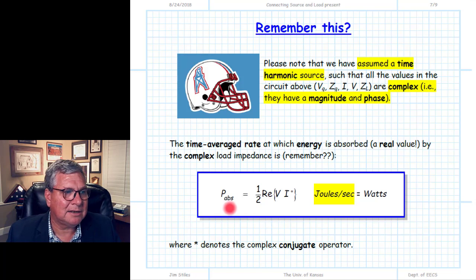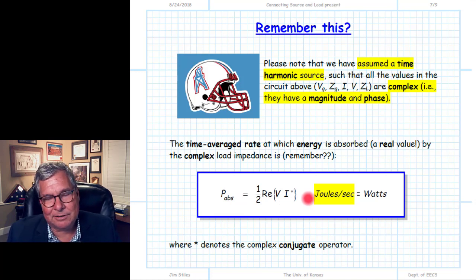And so a lot of times I get power is equal to V times I, multiplying a complex voltage times a complex current, and that's the answer. That's wrong in many ways. Again, you get a complex number, it has to be real, it has to be time average divided by 2. Make sure you take the complex conjugate. Lots of mistakes happen here. Make sure you understand, we're not talking DC.